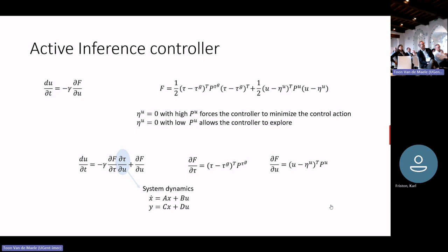Yes, it has to come from the system. So imagine it's a humanoid robot and you just wanted to control the knee joint, just wanted your leg to follow a ball to kick, then that becomes your task variable. And if your input is the motor velocities of your joints, then your system dynamics should tell you what this changes. If you put a small change in your U, how much would your toe move? That always should come from dynamics, and you have to somehow get it, and it's very difficult.